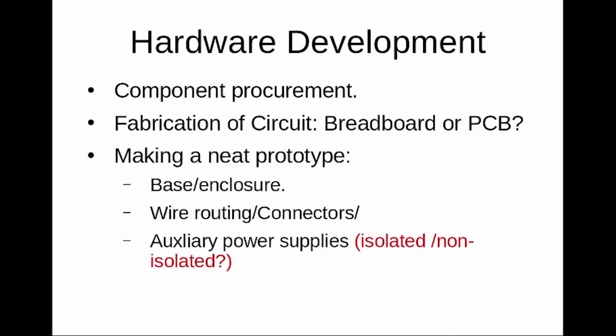A project hardware should be feasible, reliable, and a cost-effective circuit. Circuits that are handling small currents and voltages can be reliably operated even if they are built on a breadboard and are wired well. The proof of concept can also be done on a breadboard. However, if the circuit involves very high frequency switching, then the parasitic inductances of the wires and the parasitic capacitances present between conducting points may cause unexpected behavior.